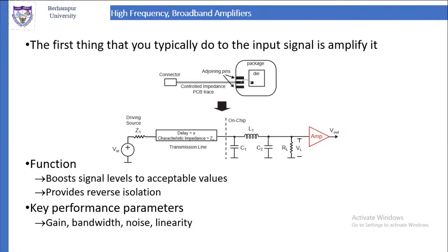Now on the mobile phone you cannot hear this. If you directly demodulate that, you are not going to get any useful signal, you will get only noise. So what you have to do is, after the antenna you have to put an amplifier to amplify the signal. So typically the amplifier is the first unit after the antenna. The main unit is the amplifier.